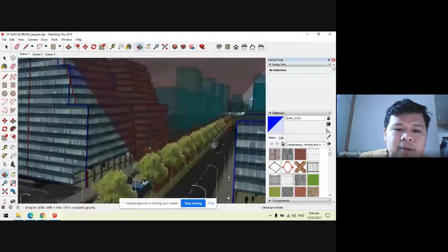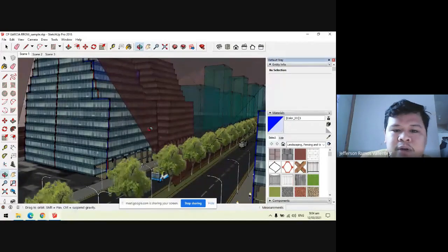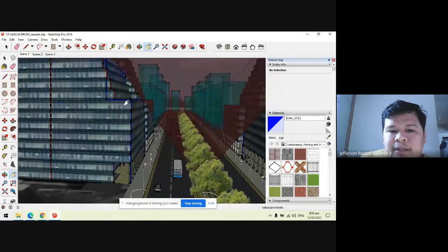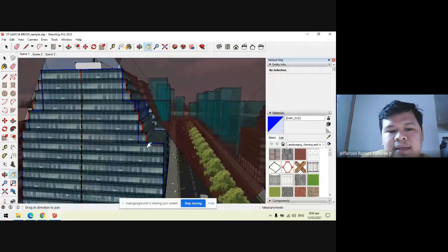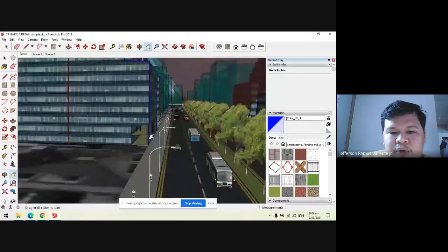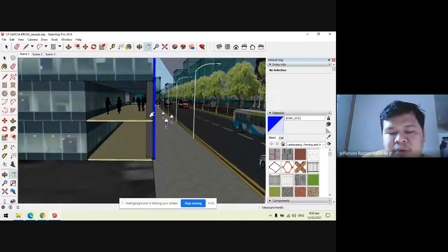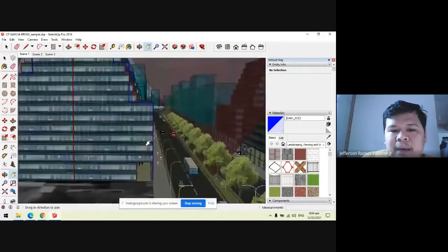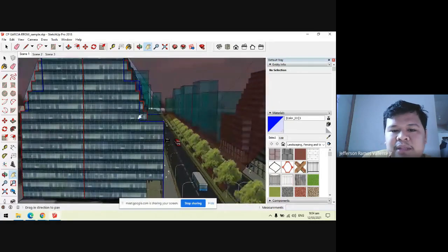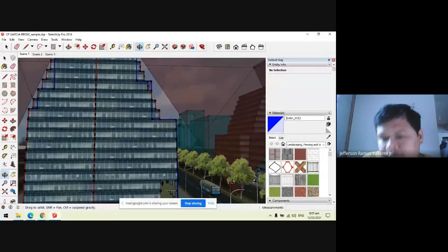So in the building code, when it gets very tall, this is 2, 4, 6, 8 stories. At the 8th story, you need to decrease the size. Because each individual has the right of access and view to the road. If you go fully vertical there, and you occupy your property line, you notice the property line is occupied. When you go above 8 stories, you should slant it or taper it a little, to allow access to a direct view of the road.